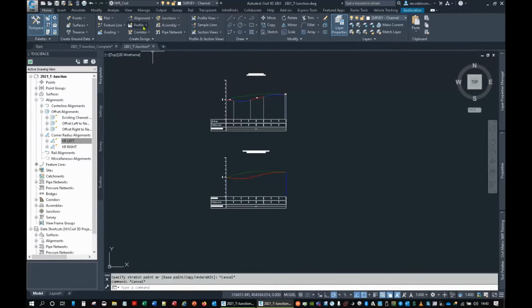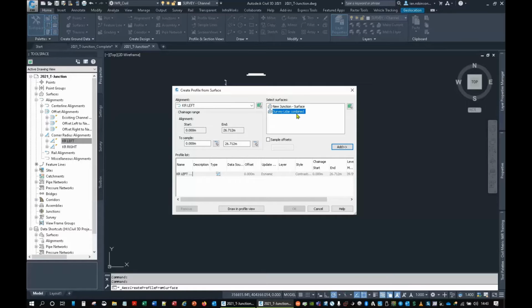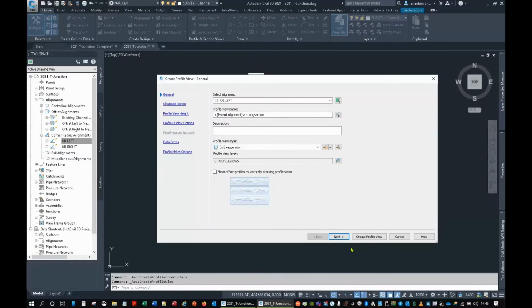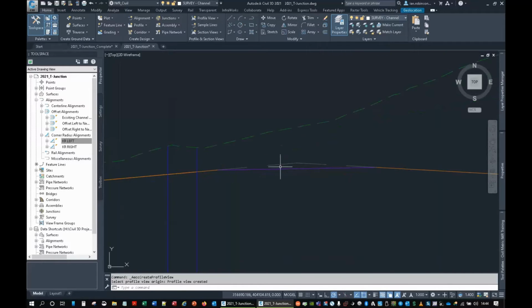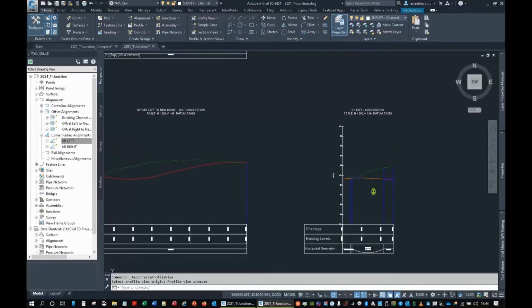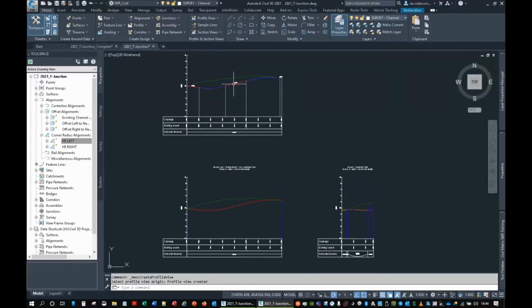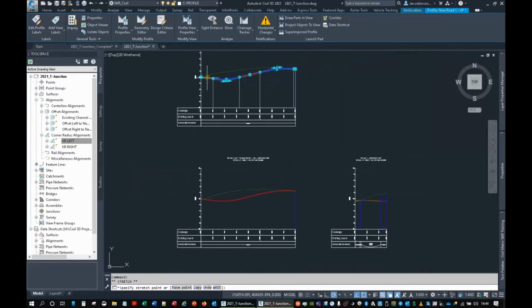Similarly, if I was to do a surface profile, and pick curb return left and add the survey in and draw that, okay, it did manage to get them little curves in. So it's got a little curve in there, but that's the vertical design tying in. Now watch what happens if I pick, I'll do that one, move out, zoom down. You see it update down here? Keep one eye on that one.